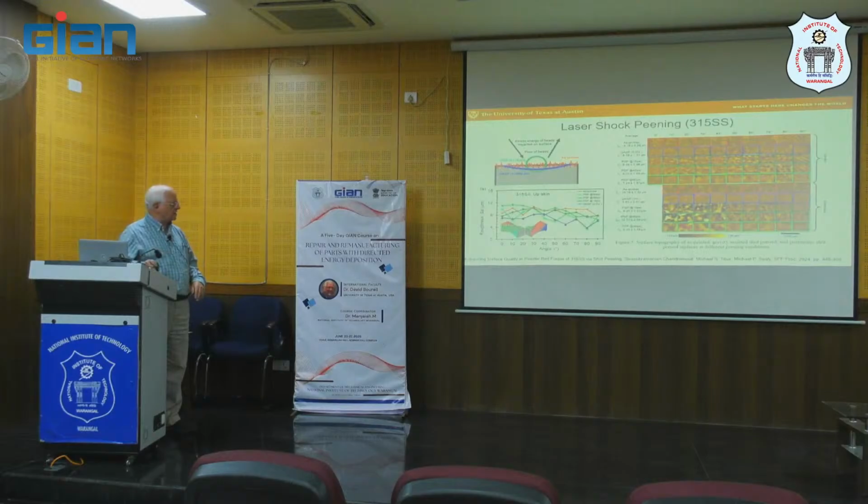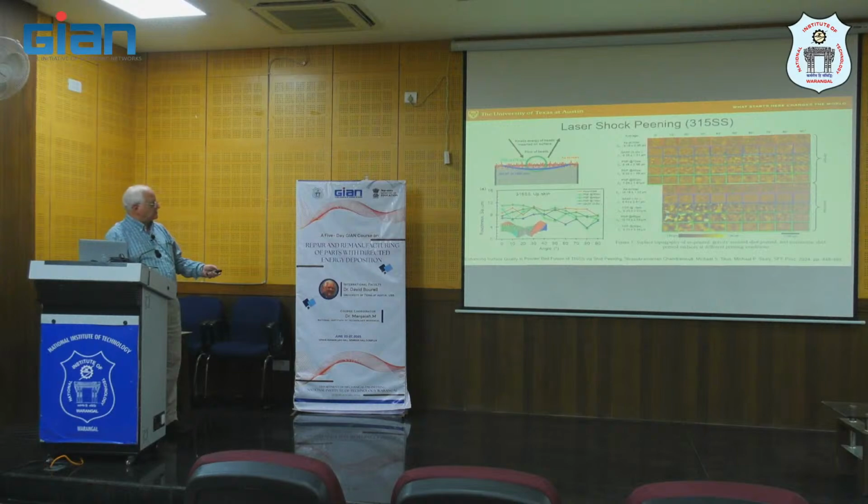There's a 3/16 stainless part that they show with the laser shock peening, and basically the upshot is that even depending on the angle presented to the laser, because the laser is always traveling in Z but the surface that it hits can vary in angle, we can see, depending on the rotation of the surface being shock peened relative to the laser, looking at the blue triangles, that it's very low, and we're able to reduce the surface roughness of the part at all angles.